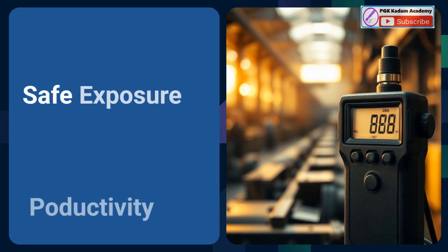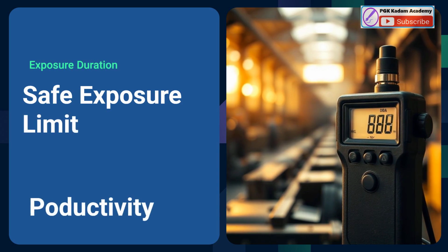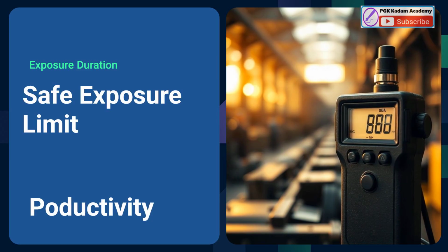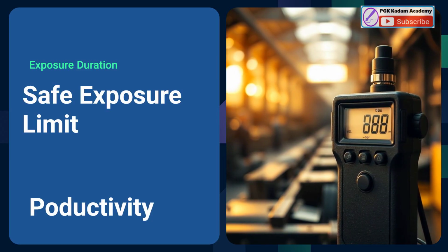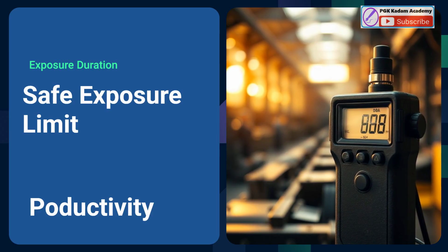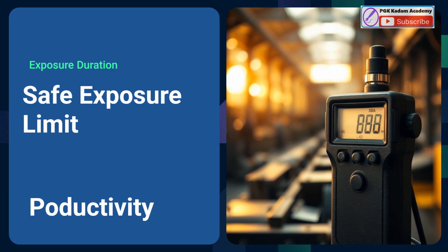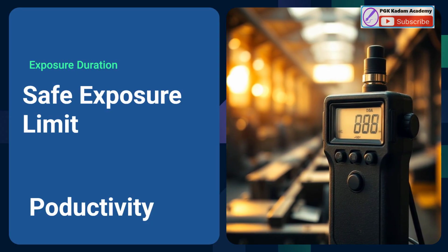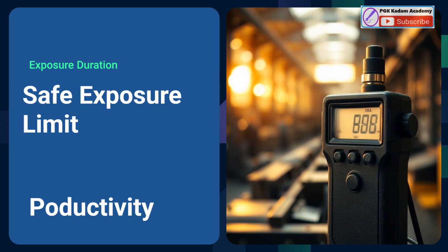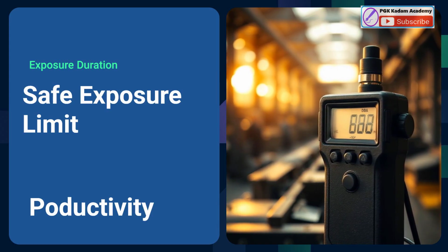Below 90 dBA, 8 hours of exposure is safe. It is unsafe to be exposed to 100 dBA for more than 1 hour. For optimal workplace conditions, noise levels should be maintained below 85 dBA when possible. Hearing protection should be provided when noise levels cannot be adequately controlled through engineering solutions. These principles used for work system design help in increasing efficiency and ultimately increase productivity.